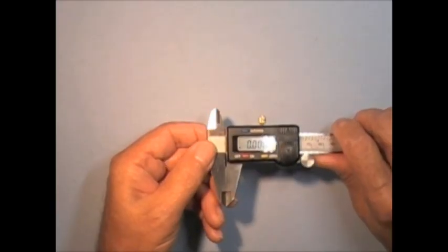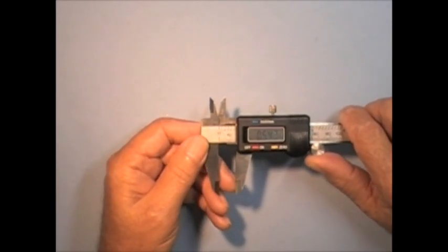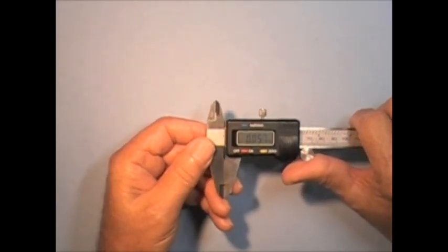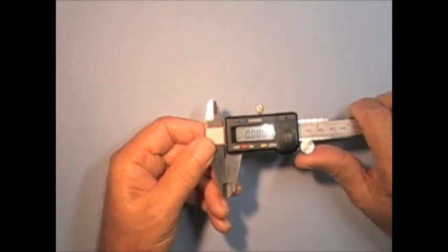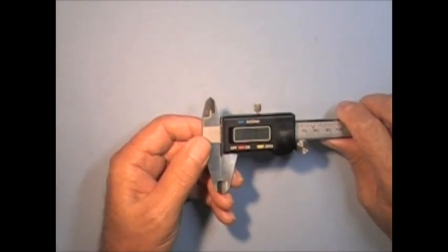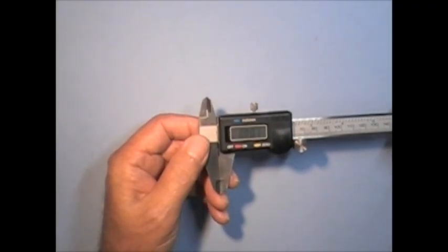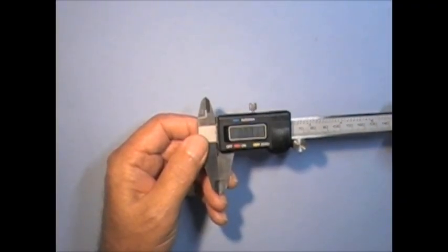One of the tools we'll be using in this course is the digital caliper. We're going to use this to measure pins with. You can measure bottom pins, top pins. You can measure depth on a cut of a key. You can do it very quickly and very accurately. These have come down to where you can get these now for under $20, and I highly recommend that everyone has one of these tools in their tool set.